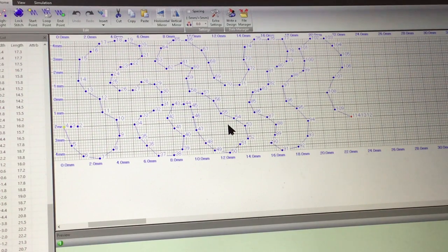That is a stitch file that will be read by the machine and which can be used as a decorative stitch on the sewing side of your machine. In addition to that, an STX file can also be opened up in either the embroidery edit side of the Horizon Link Suite program, and it can be made into lines and circles. Or if you have purchased the AccuStitch program, you can use one of these stitches also in AccuStitch, and you can create different shapes of objects for the embroidery side of the machine. But for what we're doing right now, we're talking about how do we get this stitch over into the machine.